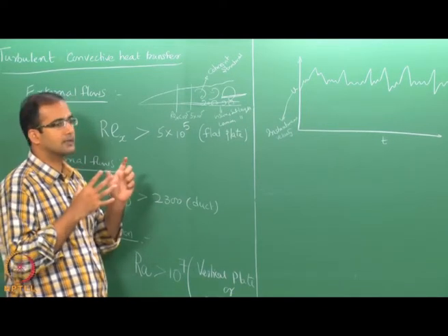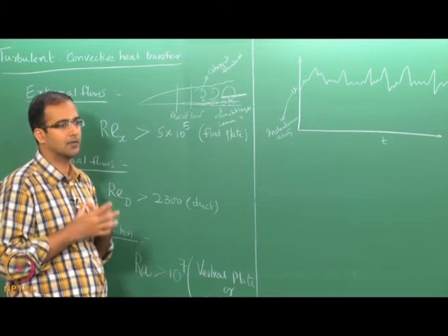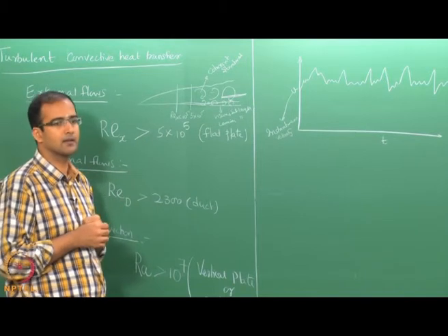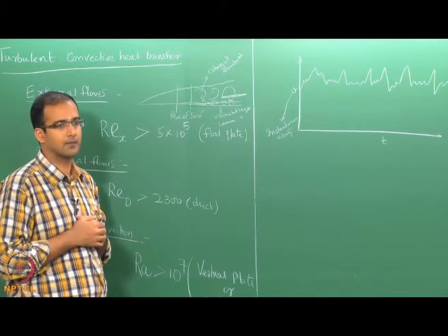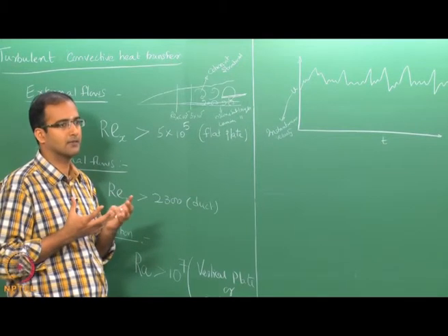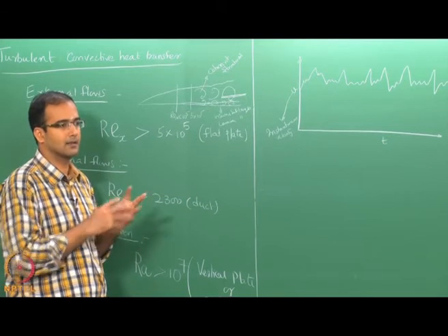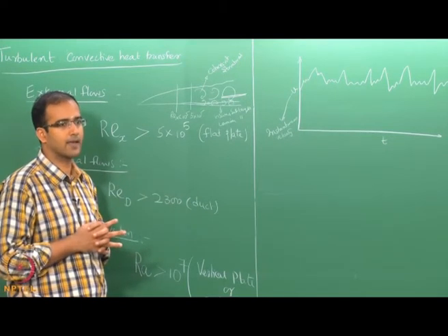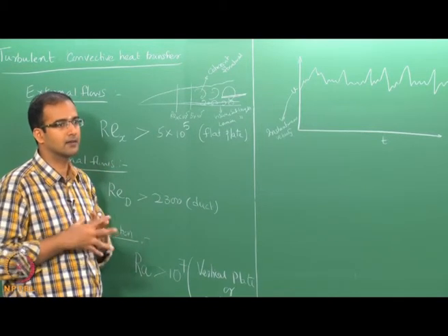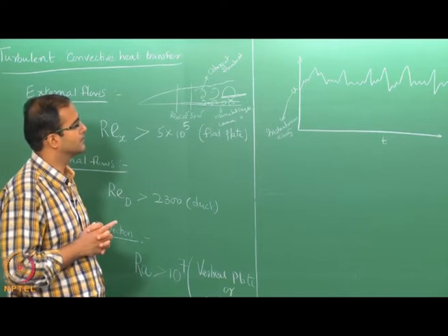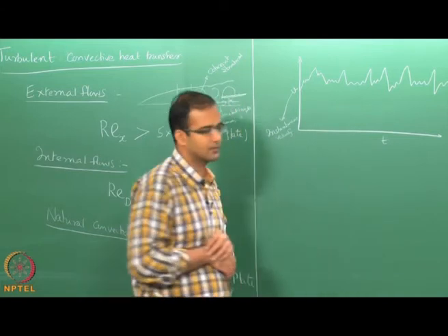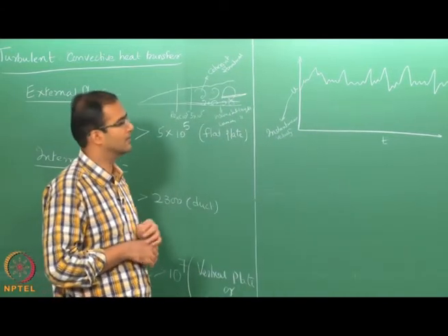Now, these fluctuations represent that there is inherent turbulence in the flow field. Okay. In a laminar case, you would not see these fluctuations, it will be a constant value at that point in time. Initially there could be some unsteadiness, but finally once it reaches a steady state condition, it will not change. But in the turbulent case there is nothing like a true steady state, there will always be an inherent fluctuation that you will observe, and therefore this represents the nature of the turbulent flow regime.